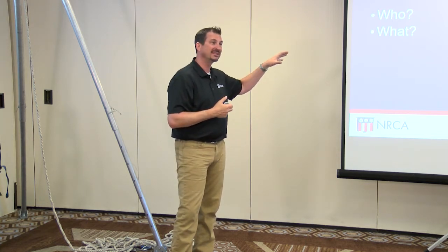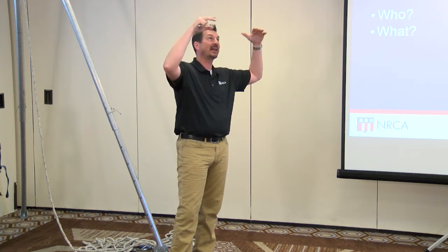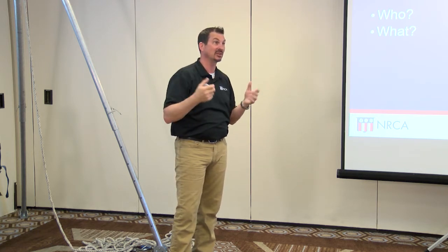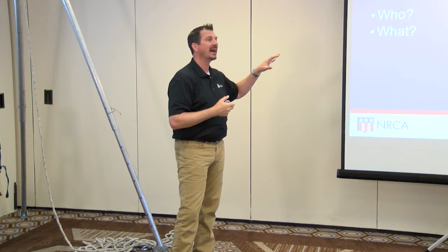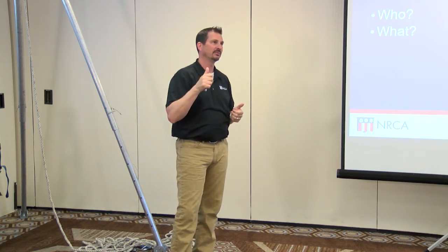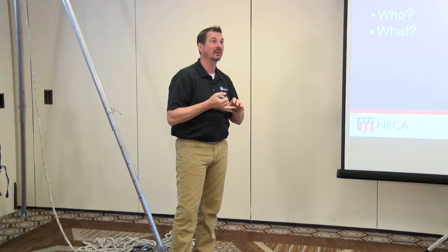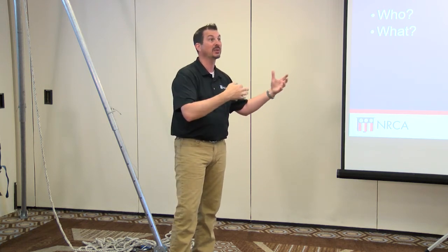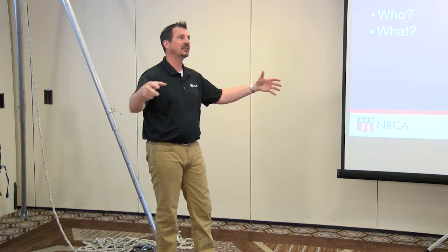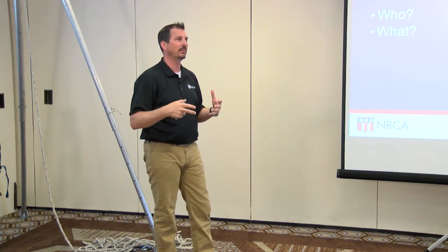After I've performed the inside facility look, and I've gotten up and maybe pushed up some ceiling tiles to look at the underside of the roofing deck, I can then go onto the roof itself. All right, and I inspect that whole roof area for mechanical equipment, electrical lines, whether it's gas lines, whether it's ammonia lines or piping that's up on the rooftop. I can then determine what's going to take place on that rooftop.